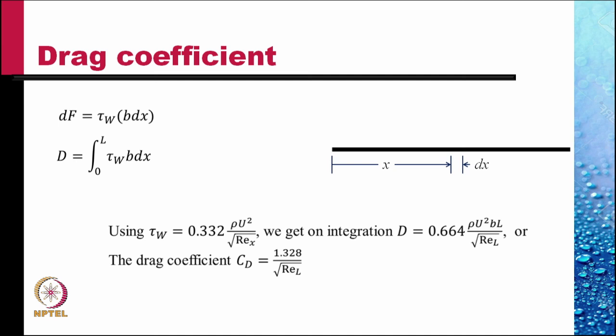The error that we should be contributing should be of the order of viscous effects, and since viscous effects are small, the error should be small. We predict a drag of 0 and we obtain a drag which is like 1 over under root Reynolds number for large Reynolds number. So there is no paradox involved here. The drag is small.